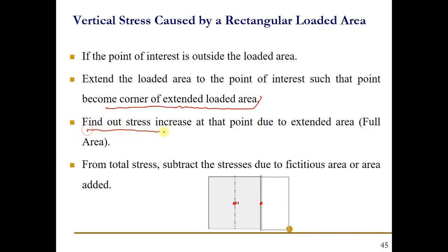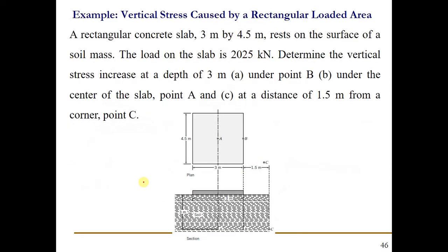We need to find out the stress increase at that point due to the extended area. We'll find out the stress increase for that extended area for the whole rectangle, and from the total stress we need to subtract the stress due to the fictitious area, and that is the fictitious figure or area which is added. So let's solve a problem related to the rectangular loaded area.